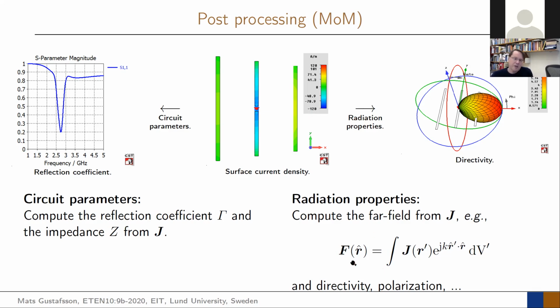So you can compute this radiation vector, which is basically what this software is doing. So the same integral that you are solving here, this Fourier transform type integral with its phase factor, that is done in the software. So they are computing the same thing you've been doing there. And that gives off this radiation vector, and from the radiation vector you can get the radiation pattern, you can get the radiation intensity, and you get how this one radiates. So that is done inside of the software.